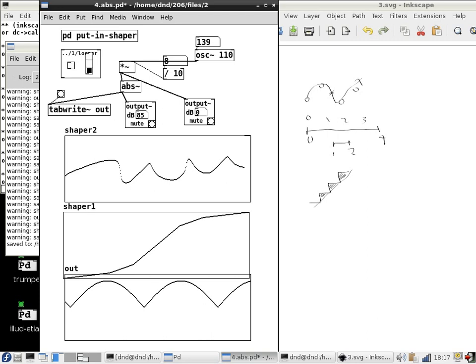This has one really good property, which is exactly what I was trying to claim you could sort of do with clipping, which is you could arrange clipping functions so that things kept on having kinks in them, but at least in the large, you didn't have radical changes in gain from one gain range to another. That's also true of the absolute value, because the power that goes out is exactly equal to the power that goes in. So I can make the oscillator louder or softer, and I get no timbre change at all.